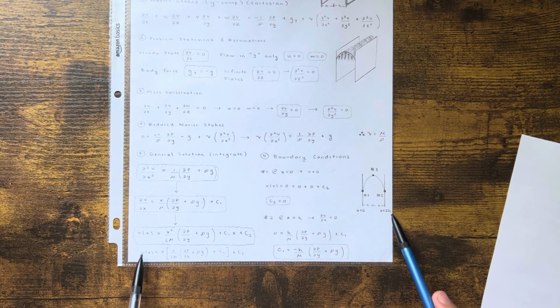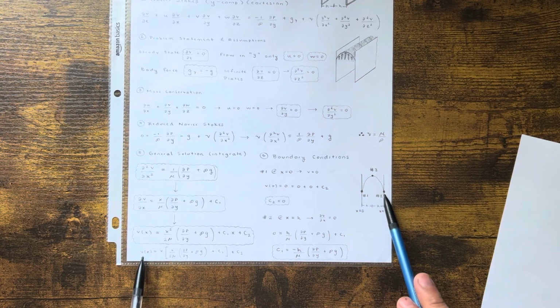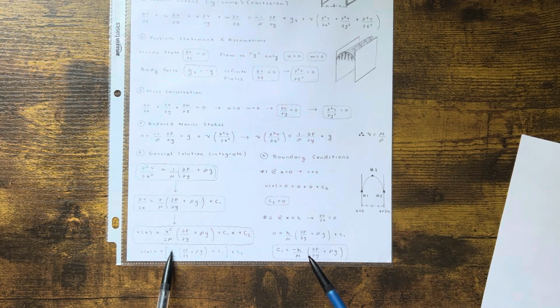Divide x to both sides. The reason, this is 0 right here, remember, right? Velocity is 0 at this location. So this is 0 divided by x, well, the x just goes away. Now you put in, for every x that you see, you put in 2h. So 2h over 2 mu will give you h over mu, right? Plus times all this plus c1. Well, now solve for c1, so move all this to the other side, it just becomes negative. And you get negative h over mu, parentheses the constant, okay? That constant right there.